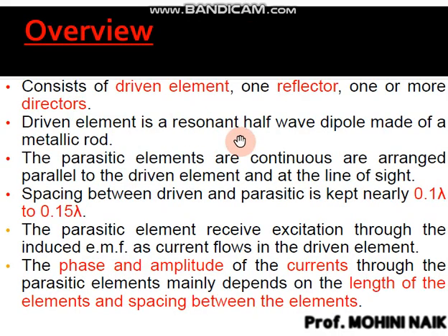So the driven element is a resonant half wave dipole. Half wave dipole meaning what? Half wave, lambda by 2. What is lambda? It is related to the frequency. Suppose I am designing a television transmission, and the frequency is 30 megahertz, I will have to calculate its wavelength, and wavelength divided by 2 will be the length of your driven element.